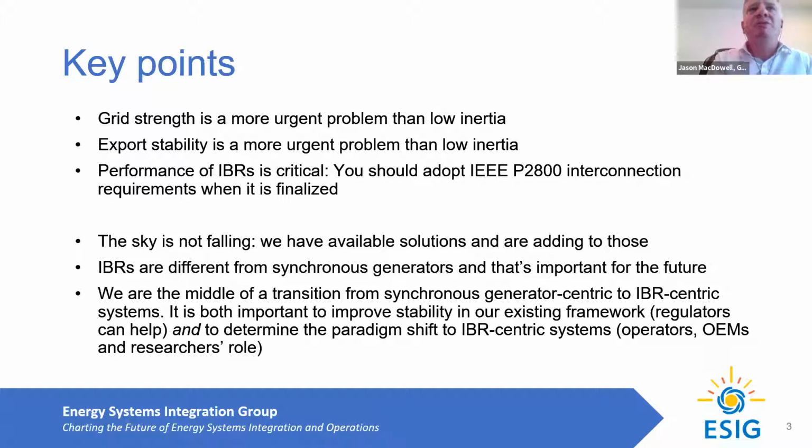But the notion of grid strength, how relatively dominant inverter-based resources are in any particular area compared to synchronous resources, is more of an urgent issue than the frequency problem is. And the coordination and interoperability of all resources to be able to manage that is critically important. We'll get a lot more in depth on what that means.